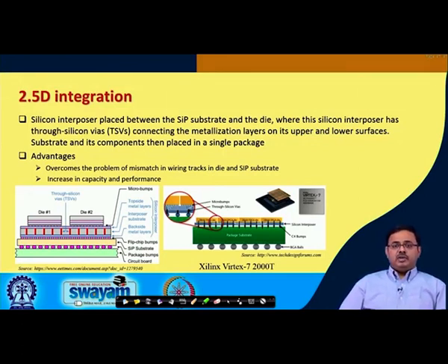It is like, for example, you are driving a car on a wide road and suddenly you have to enter a narrow lane. So, of course, there will be a kind of bottleneck and traffic jam over there. So, smooth flow of traffic will be hampered. So, same case here, if your wiring traces where they connect have a lot of mismatch in terms of the wiring of the tracks and its dimensions, then it will impact the flow of signal and signal integrity.